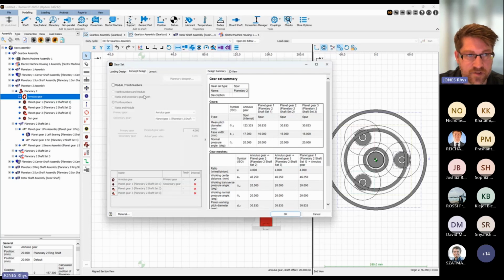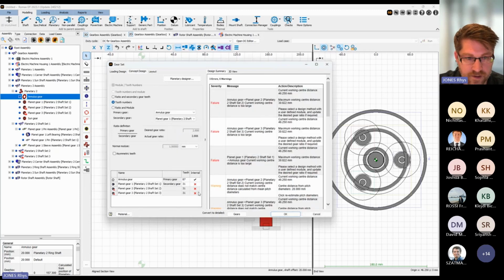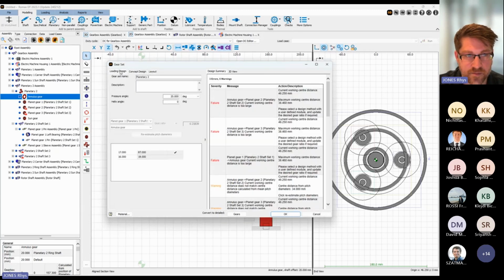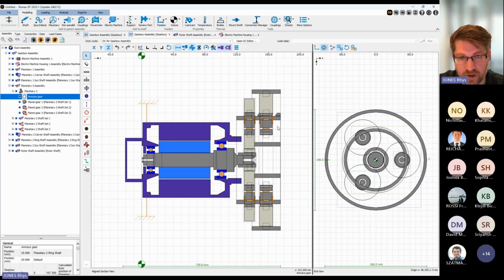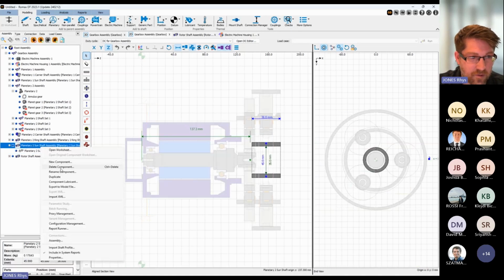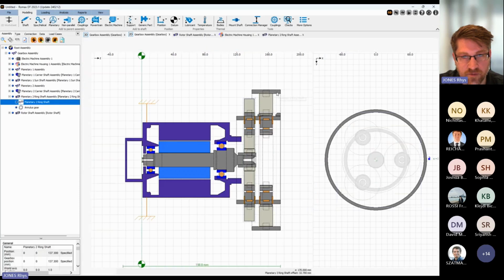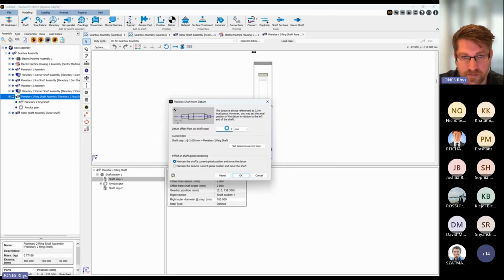And under the concept design, we are going to, again, define our tooth numbers for our annulus and our planetary gears. And again, we get our failures, so we're going to re-estimate those pitch diameters as well. So now we have the annulus and the second stage done. We can delete this sun gear shaft because we don't need it. There's no gear on it. Delete that component. And we can start to make some changes to the ring gear. Again, check the datums are at 0.